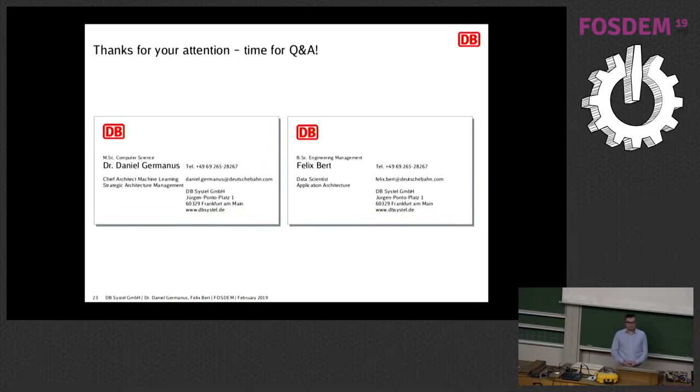So the question was why we are actually using acoustic data, and if it can be put on rolling stock. We are aiming at a universal platform which can be fit into various machineries, and there are plenty of regulations in terms of modifying machinery. So this is non-intrusive. We just pick up the acoustic emissions. We do not have to change the machinery itself.